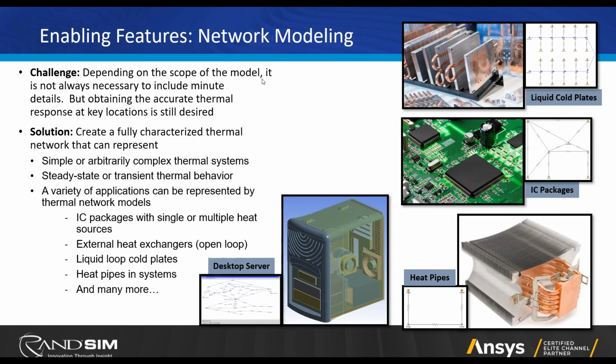So network modeling. This is what was referenced by reduced order modeling here. What this allows us to do is make a thermal resistor network which models various designs. In these, the nodes would represent different portions of the design. This would be constructed by doing the actual CFD simulation in many different circumstances, and then constructing this simplified model from that point.